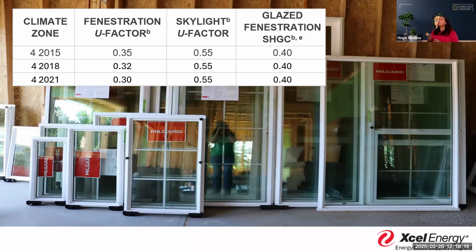But when you go into one of the Manual J softwares, whether it's RightSoft or Elite or Cool Calcs, whatever type of software a designer utilizes, when you put that information in, you're either classifying it as a skylight because it's less than 60 degrees, or you're classifying it as fenestration, and it takes that into account.